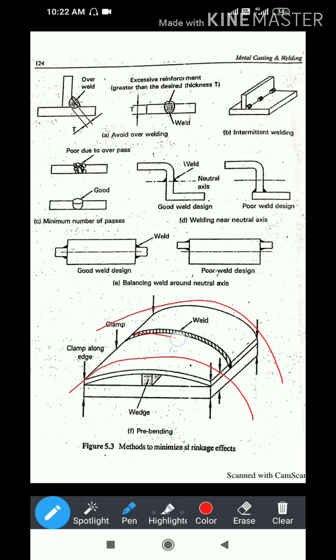But when the weld gets solidified and cooled, after the fusion the welding deposit material starts to cool. When it solidifies, obviously the shrinkage of that welding material also occurs. When it undergoes the shrinkage effect, the shape of the sheet may change.